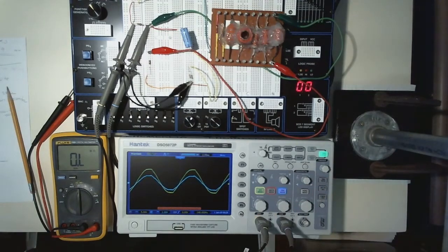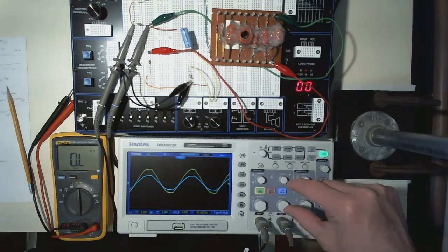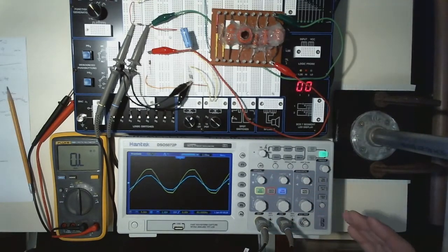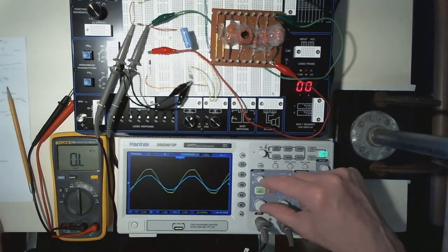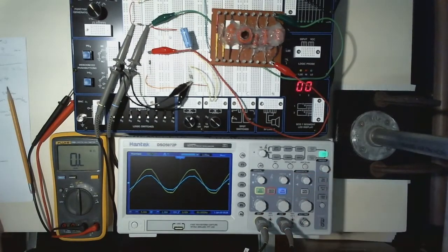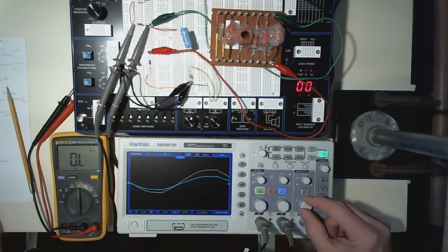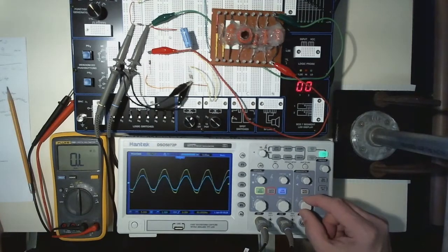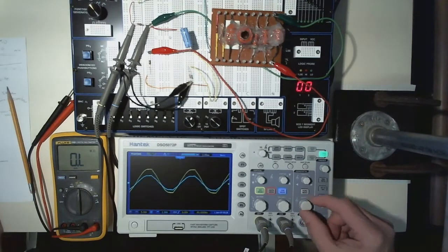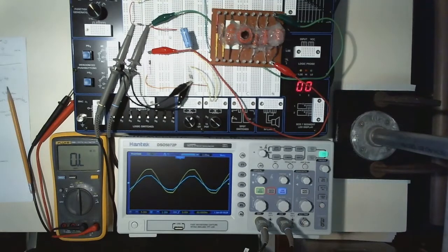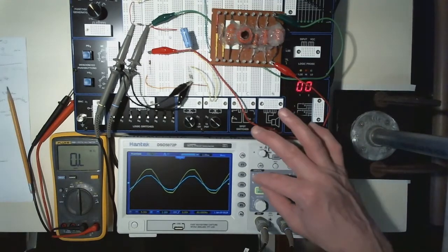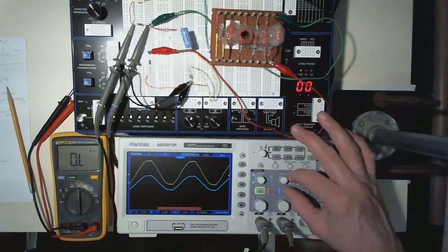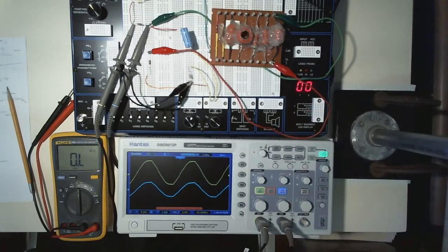And looking at any oscilloscope, it's usually arranged this way. It'll have channel 1, it'll have channel 2. It might be multi-channel, but if it's 2 channels, very common. Channel 1 here, channel 2 here, and then your time base. You can control your magnification in the horizontal. Okay, like that. So when you walk up to the oscilloscope, a lot of times it may be something like this, and there's